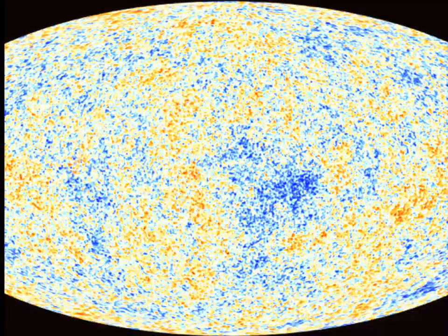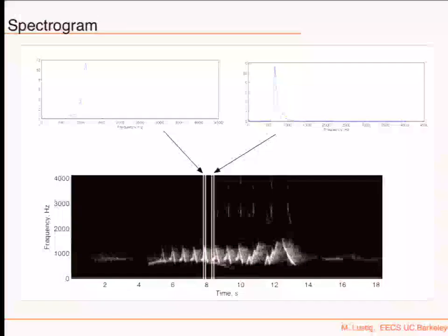So we talked last time about spectrograms and the short time Fourier transform. When you look at a spectrogram, there's time and then the frequency space. So you map a one-dimensional signal into a two-dimensional space. You start with one index, and then you get two indices: one corresponding to time, and another corresponding to frequency. And it gives you very interesting information about the signal.